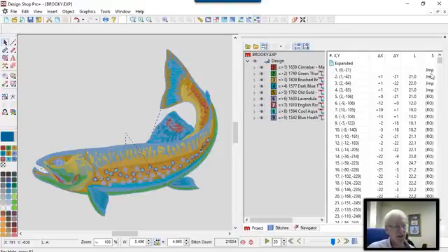So here you can see in the stitch list we have each individual stitch, and it's X, Y, as well as the length. This is a very important column when you're looking through designs to find out, well, why is this going so bad? If you see clusters of tight stitches at 3 and 4 and 2 points and all this, it's going to give you trouble. Mainly, I see a lot in the tie-in stitches. It will go slingshotting because it is going through the same hole.